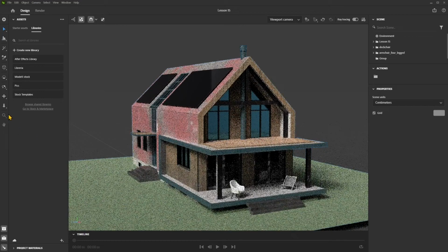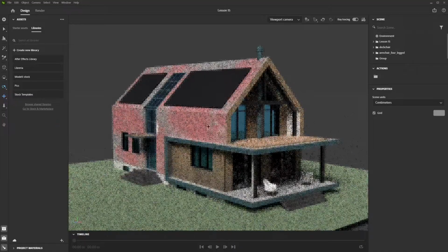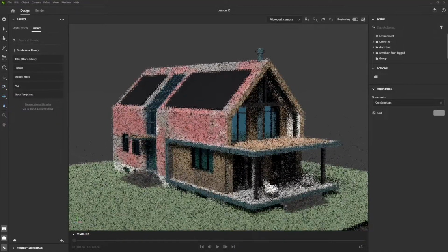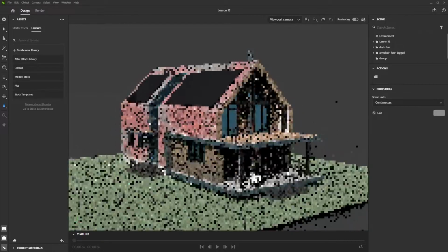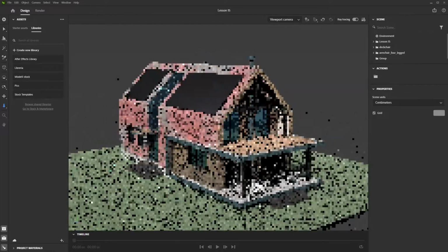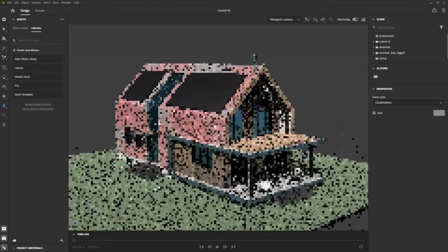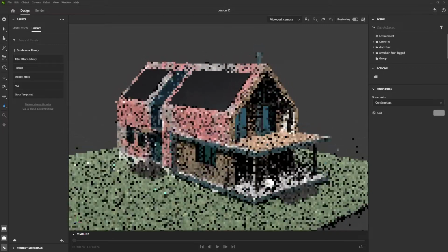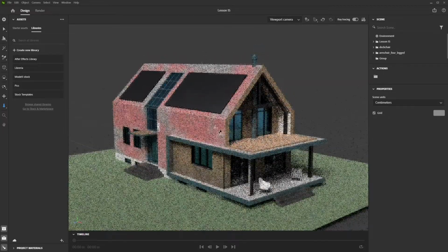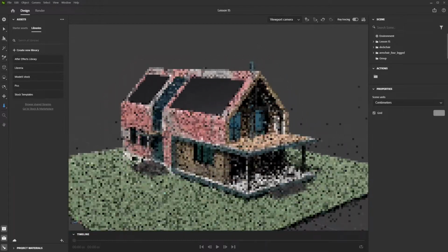Now the first thing is the navigation. You'll find here on the left side this toolbar where you have all the tools. So you have the navigation, orbit, and panning and zooming, which are similar, well actually I think identical to Substance Painter. So you can hold the Alt key on your keyboard and click with the left mouse to orbit, middle mouse or scroll wheel, you can press it to pan, and hold the Alt and the left and the right, to zoom in and out.